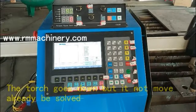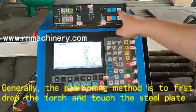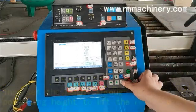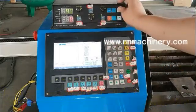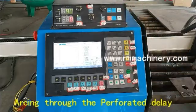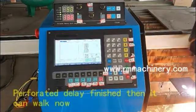Generally, the positioning method is to first drop the torch and touch the steel plate. Then set the height through the positioning height to lift and recover the arc. Arcing goes through the perforation delay. Perforation delay finished, then it can walk now.